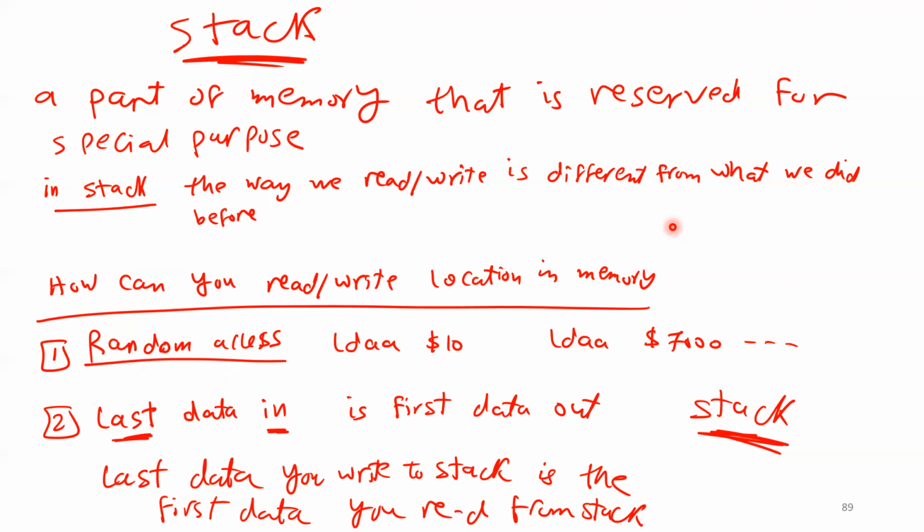Once I put 0 in this bit, the hardware is gonna put 0 volt on the pin. Once I put 1 in the bit, the hardware is gonna put 5 volt on the pin, right? And I make the hardware so that when I put 5 volt here, the electronic circuit should turn on. When I put 0 volt, the electronic circuit is gonna turn it off.